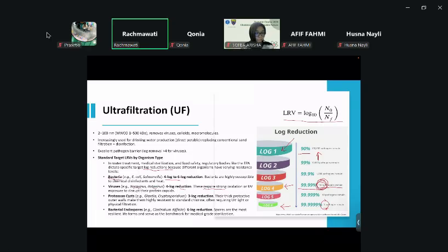And then for protozoa, such as Giardia or Cryptosporidium, the aim is a reduction of log 3. So log 3 is around 1000 remaining. In this case, their thick protective outer walls make them highly resistant to standard chlorine. They often require UV light or physical filtration.